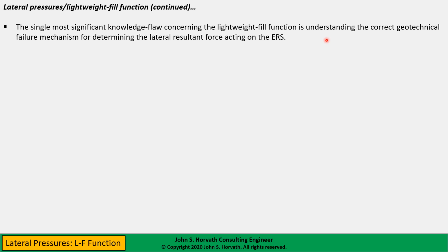It's important to reiterate that whether you use the compressible inclusion function or the lightweight fill function, essentially what the geofoam product is doing is attenuating the earth force between the soil and the earth retaining structure. So it's essential to have the correct physical mechanism by which the geofoam achieves this load attenuation.